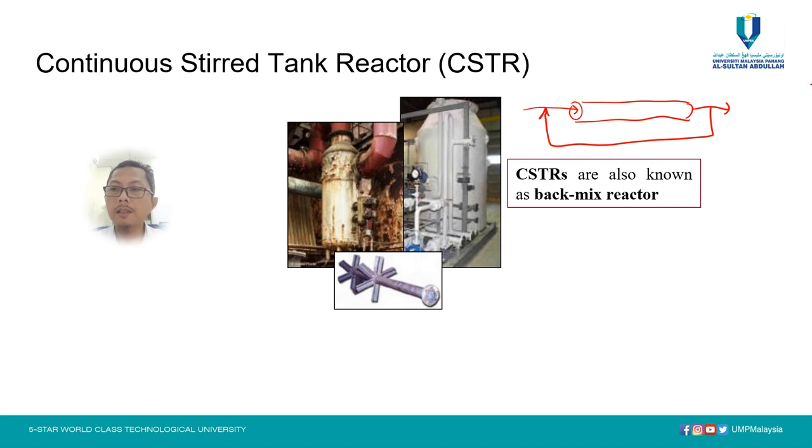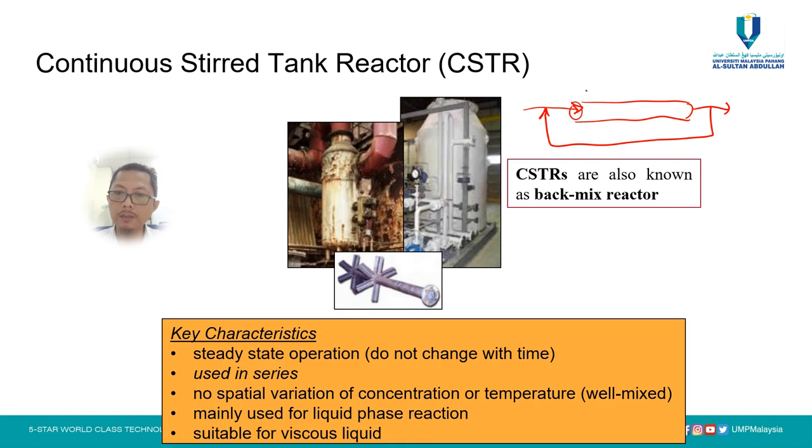This line is important to dilute the feed. The characteristic of the CSTR is that it will have low concentration of feed. So normally we have back mix flow like this to dilute the feed. This is due to the selectivity issue of the reaction normally.